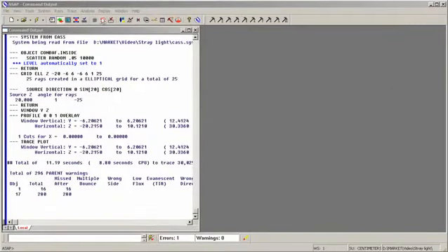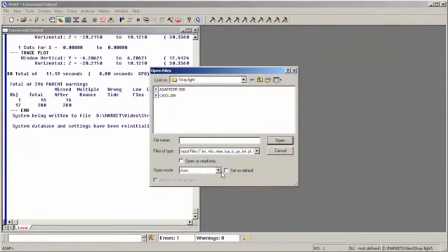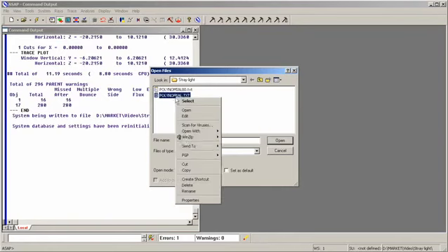Let's take our measured data and fit it to find the coefficients. Let's do this by opening up a file within ASAP. We go over here to our ASAP file. BSDF fit utility is the application that we're going to use, and we're looking for text files. I have here some text files which represent the measured data for the black surfaces that we saw before. Let's take a look at one of these text files before we first open it up.